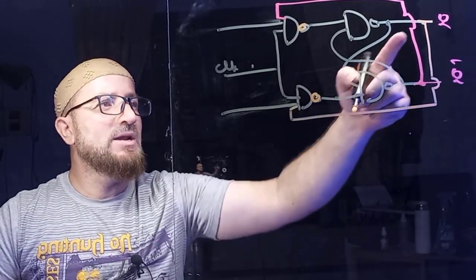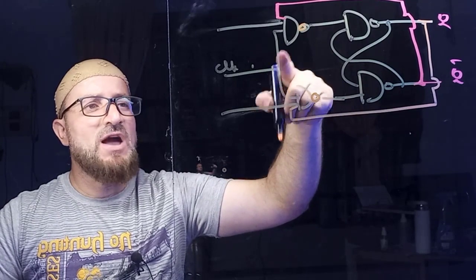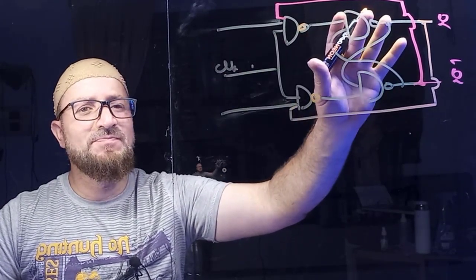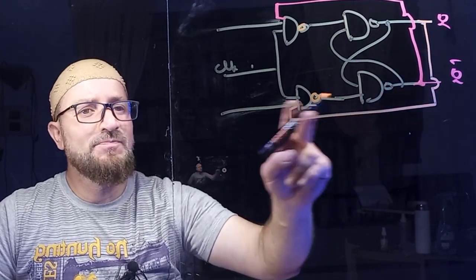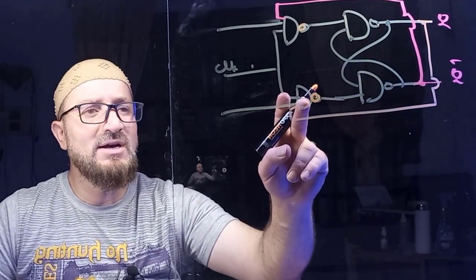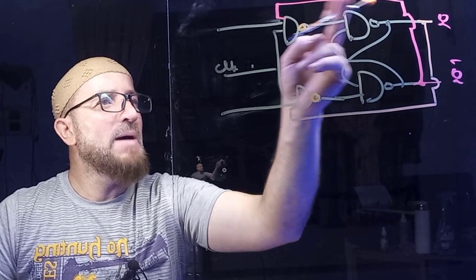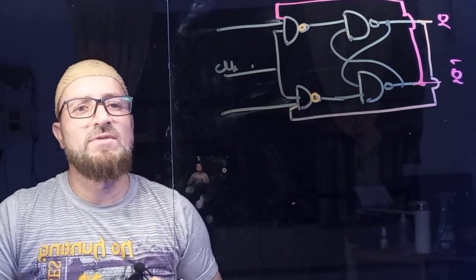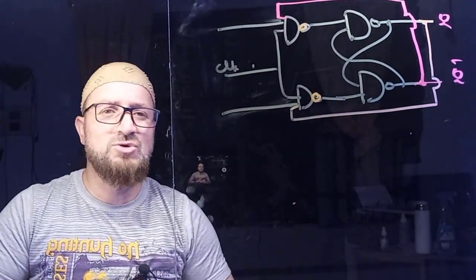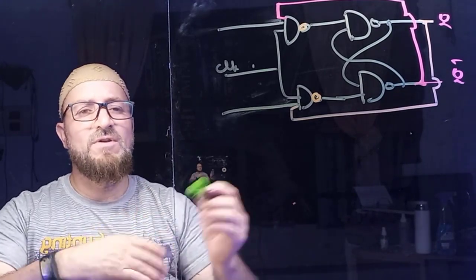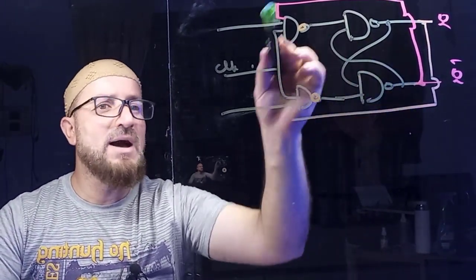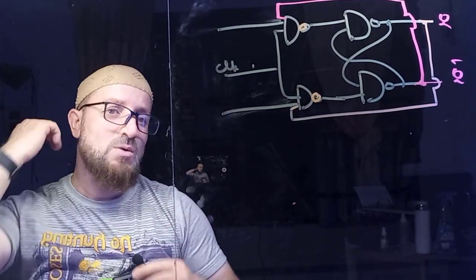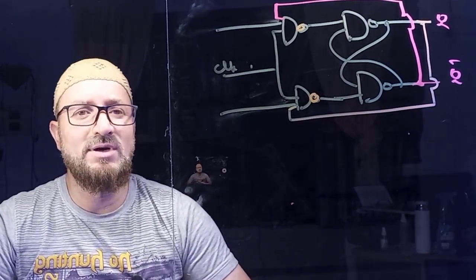If you have the same SR flip-flop, and you put up the additional loop from Q back to this gate and from Q complement back to this gate, it will become a JK flip-flop. Okay, it is so simple now. The JK flip-flop is nothing but additional feedback loops. Come back here and come back here. Simple. Now, how will it work? Let us see how it will work.